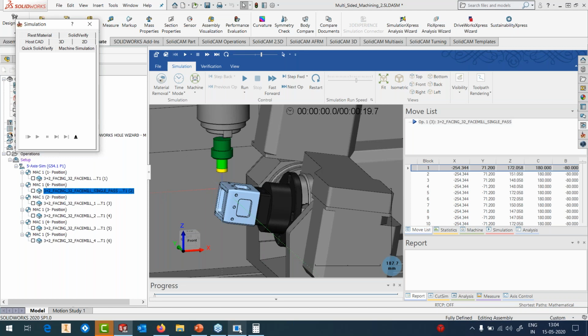Okay. We have got a special training course only for this 3+2, especially for pure angles. Okay. Someday we could have just a session for this particular, because it's pretty interesting. And there are several machines today in India that do not have the 3D coordinate rotation functions, neither they use the macros. So the only way we go here is with the pure angle method. Okay, so many of my customers, by the way, are using this method successfully. They don't look left, right. They just take the program down on the machine and run it.